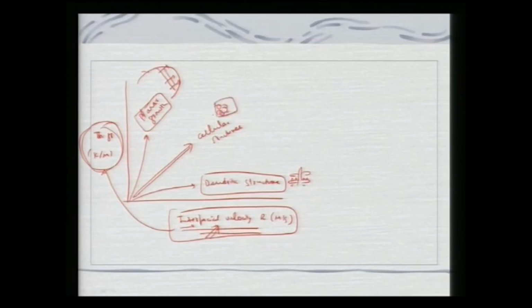So, that is the advantage of the interplay between the thermal gradient and the interfacial velocity. By controlling them I can achieve a very refined microstructure. That is the overall play with thermally sprayed coatings.